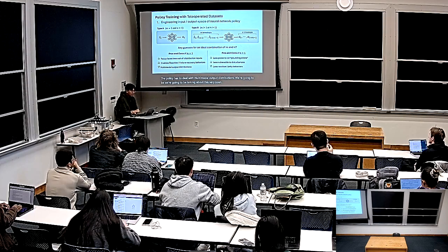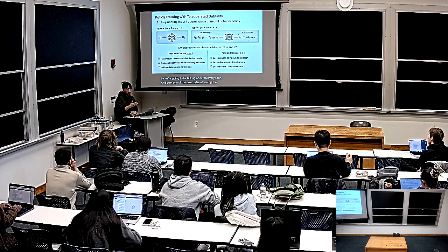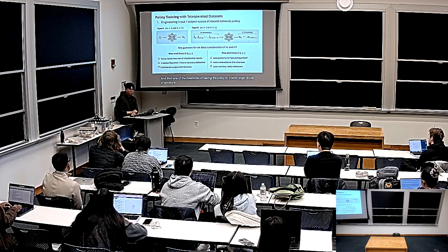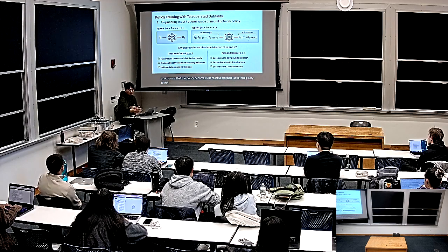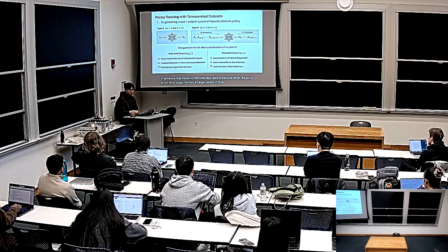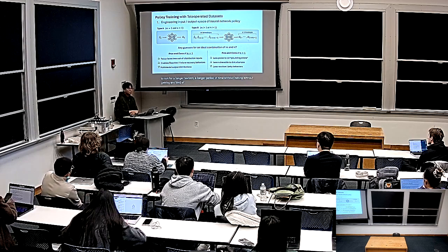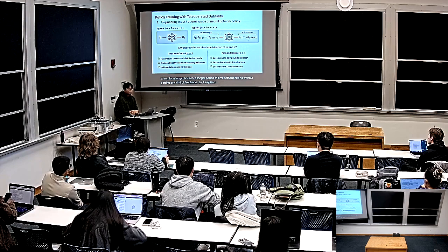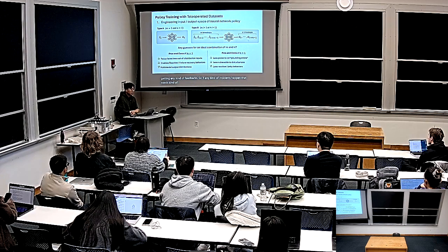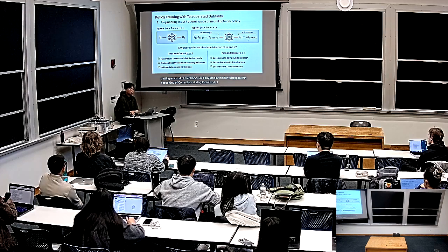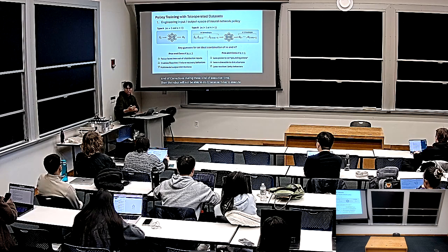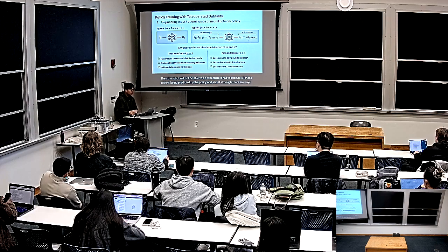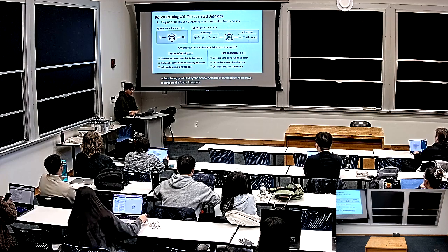And one of the downsides of having the policy predict a larger chunk of actions is that the policy becomes less reactive, because we let the policy run for a longer period of time without getting any kind of feedback. So if any incident happens that needs correction during the execution time, the robot will not be able to do it, because it has to execute all the actions predicted by the policy.